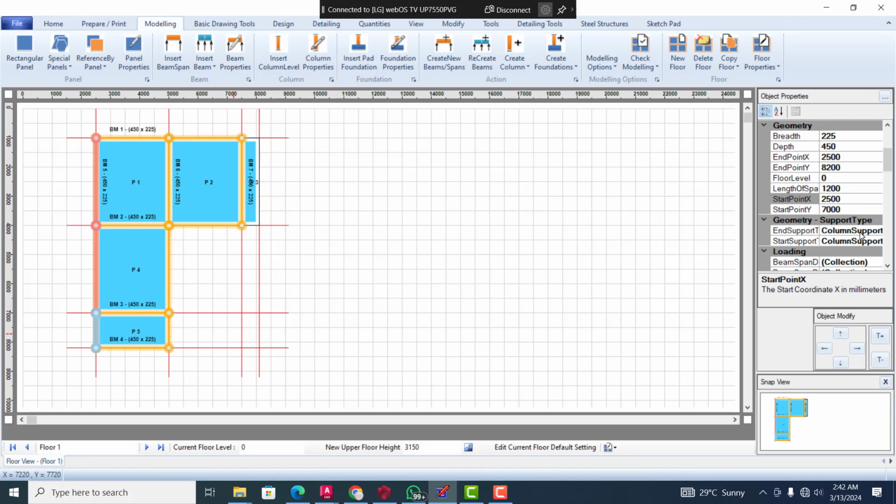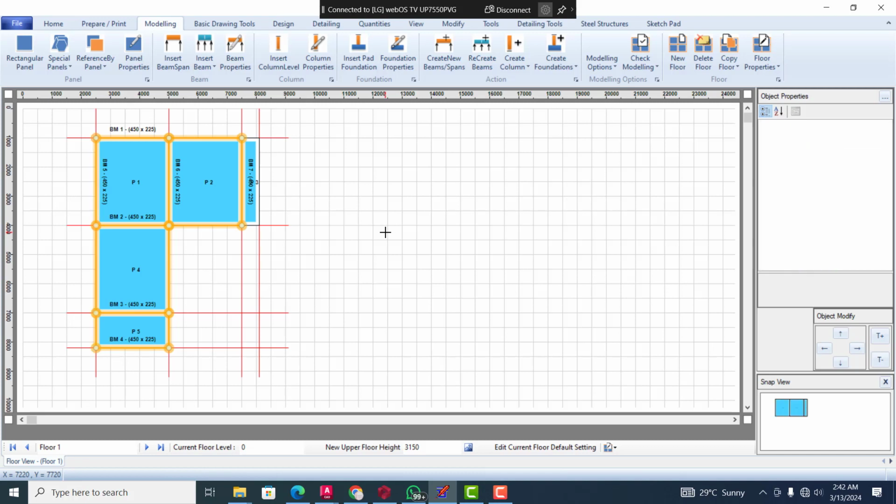So this one as well, at the end, click on this drop down menu, click on beam, primary beam support, and then we are good to go. If you look at this very well, you realize that this node is looking a bit different, but don't worry, you will appreciate it more when we create floors.